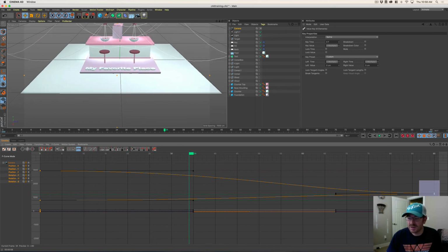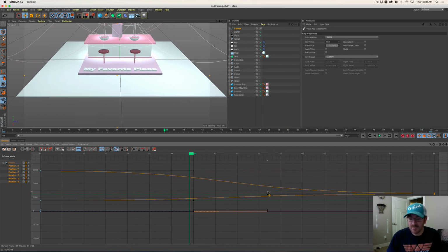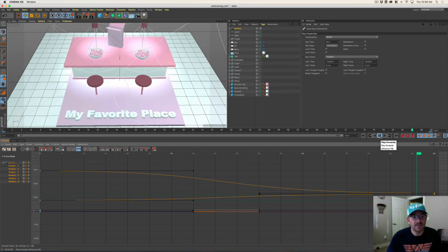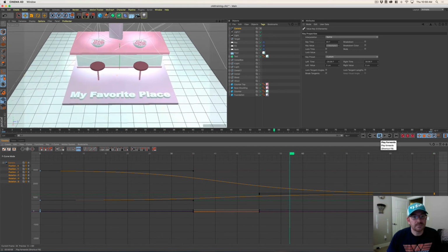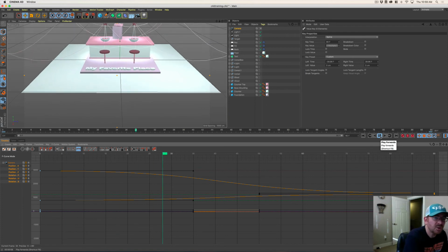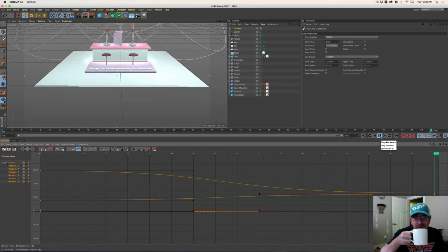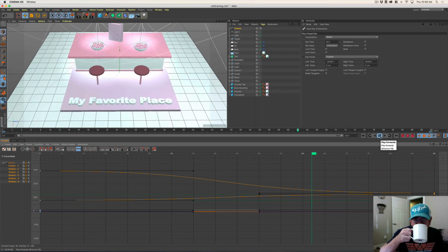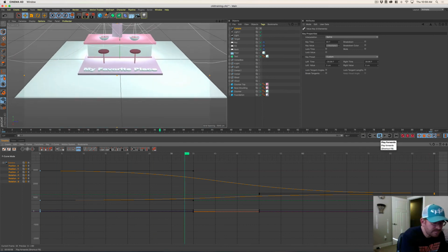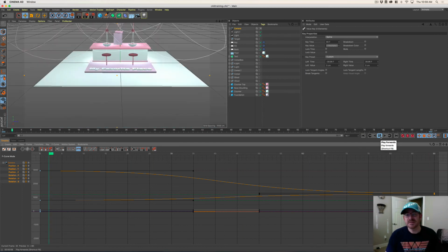I'm going to do the same thing with my end keyframes. Just press Command or Control and drag those out maybe to, I don't know, 55 or 50. So it's going to ease in and ease out really, really gently. And then play that back. Have a little coffee while that plays back. That's nice.